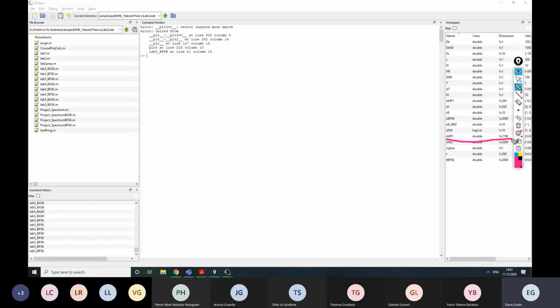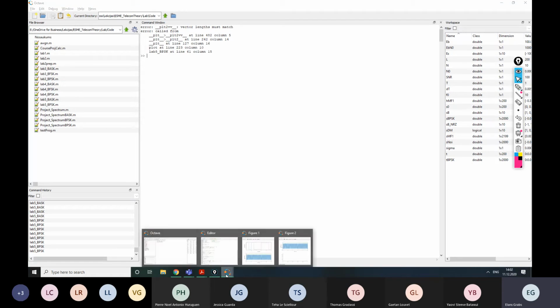So we had at the input 2000 samples and at the output we have 2199. So basically we have L-1 more samples than we need. So we need to skip the remaining part somehow, yes, to truncate it in order to match our initial signal and successfully plot it.